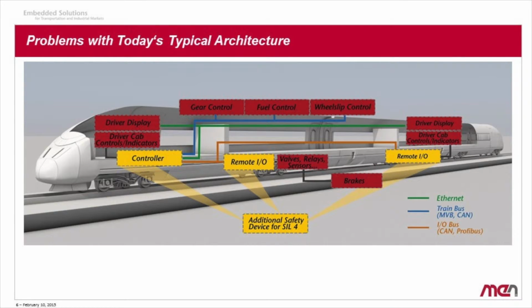Where's the limitation at the moment? Typically the limitation, as I mentioned, is in the controller unit, because that is normally built to SIL 1 or SIL 2 level. Also the I/O is only built for SIL 1. So it's very limited. Here is the biggest bottleneck at the moment, and you have to deal with additional functionality or find better solutions. Now I will try to show you how such a solution could look.